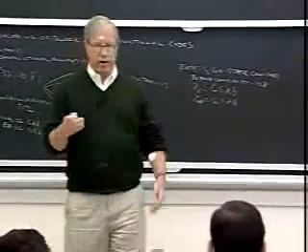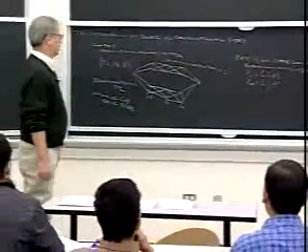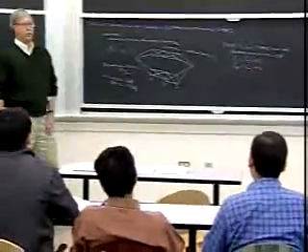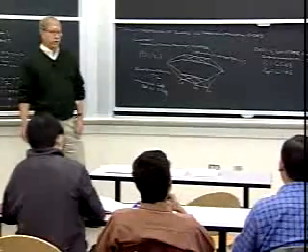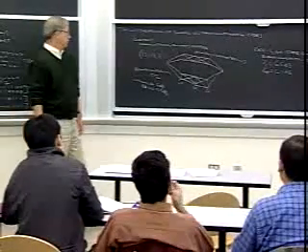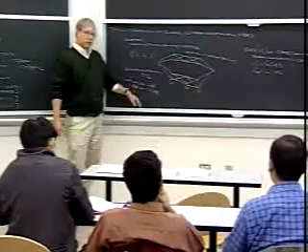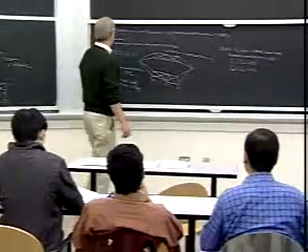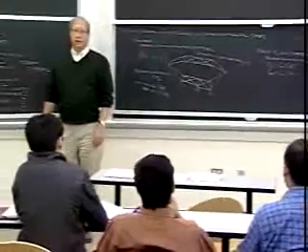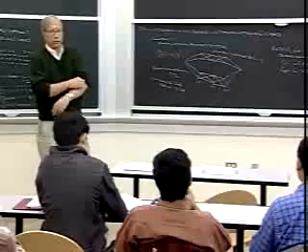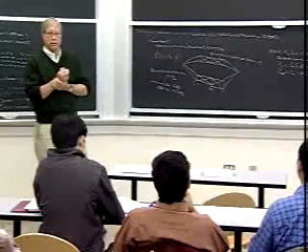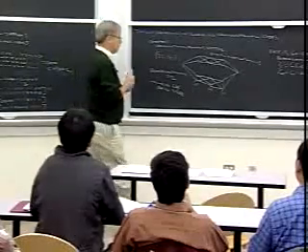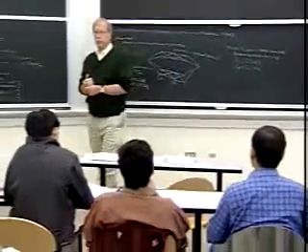If you kind of try to plot a graph of this, you'll see that the effective coding gains of convolutional codes with the same state complexity is at least 1 dB better as a general trend than that of block codes. And if you do it in terms of branch complexity, it's an even better comparison. So what happened was there was about a decade of effort on basically finding good trellis representations of block codes. And the net of it was that they couldn't get anywhere close to finding anything as good as convolutional codes, although it's a nice little piece of theory.